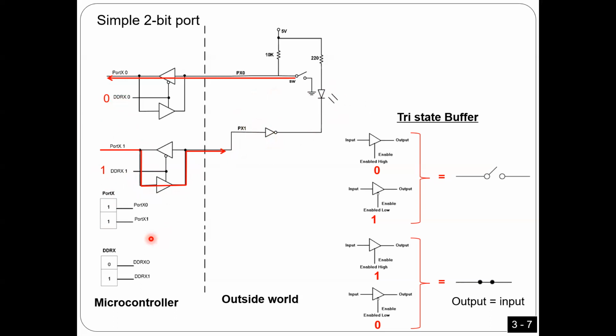Okay, I'm going to say the conclusion in one or two statements. Number 1, any port you are using in your program, you must configure it as input or output. And this configuration should be done only one time. If you have a loop, there is no need to put it in the loop, because once you configure it one time, it's going to stay there because you're not going to change it, okay?